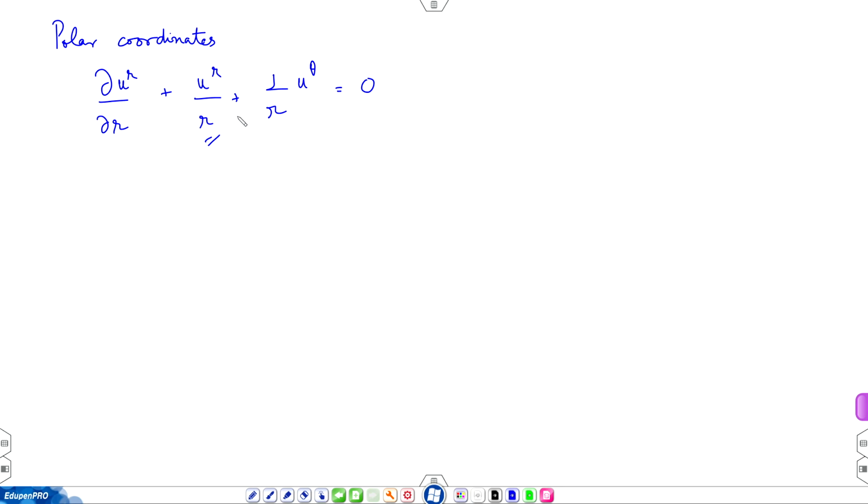So, this is del dot u equal to 0, which is the mass balance equation for incompressible flow. If the flow is compressible, then you will have the fuller form, where there is a time derivative with respect to density. It's a local description of the flow field. So, let us look at an example. Let us say I could do flow through a tube. I may also do, let us say, flow between parallel plates.